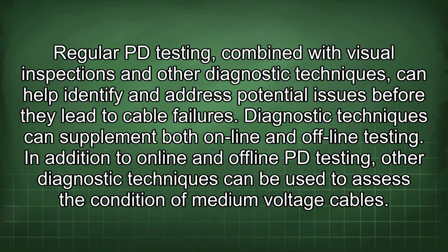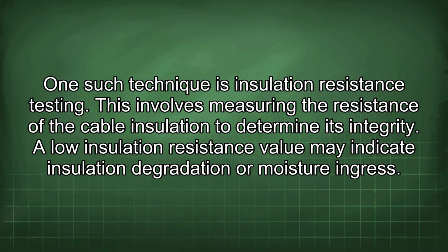Regular PD testing, combined with visual inspections and other diagnostic techniques, can help identify and address potential issues before they lead to cable failures. Diagnostic techniques can supplement both online and offline testing. In addition to online and offline PD testing, other diagnostic techniques can be used to assess the condition of medium-voltage cables. One such technique is insulation resistance testing.